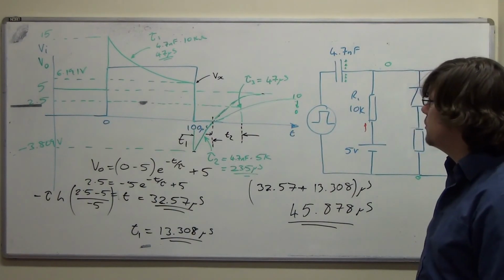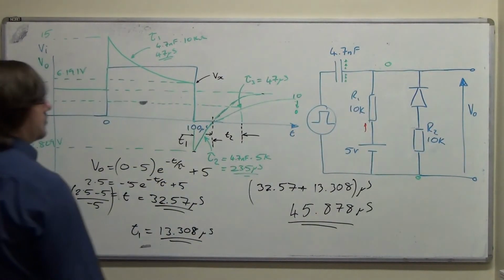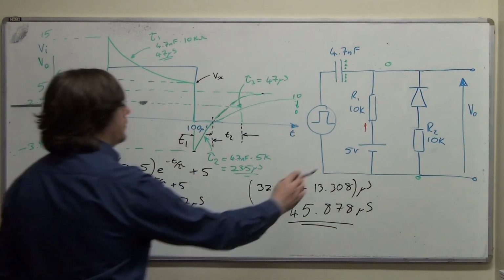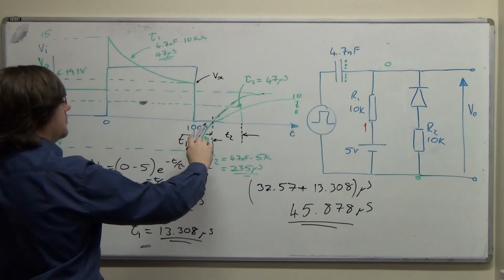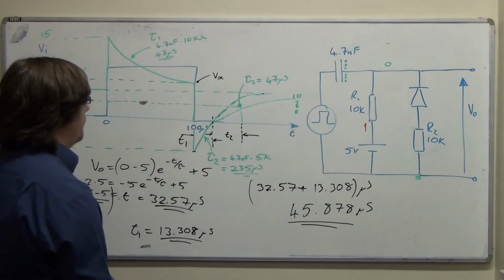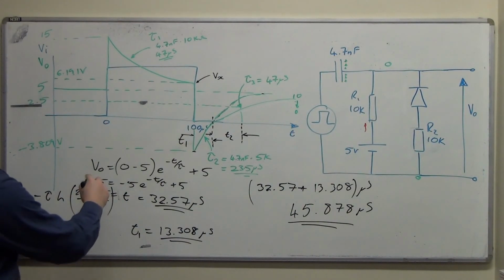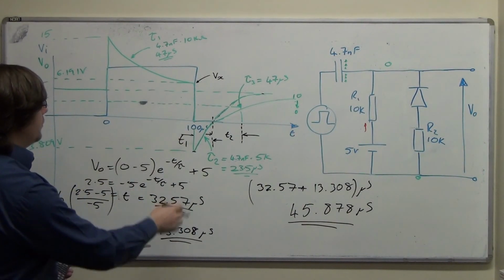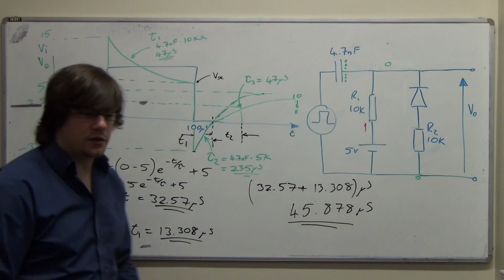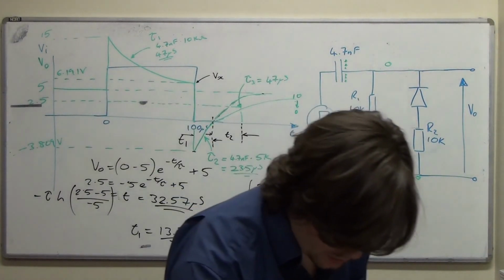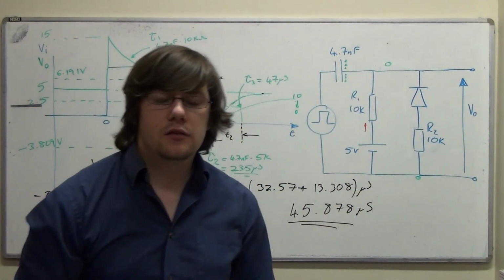And that's how you kill that one. The only thing that really makes this taxing is figuring out when the diode will start or stop conducting halfway through this recovery. Once you've got the hang of that, it's figuring out what your aiming voltage and offsets are in the exponential equations to make sure you actually get the right numbers out. And that is the end of the tutorial sheet. Sorry, problem sheet.